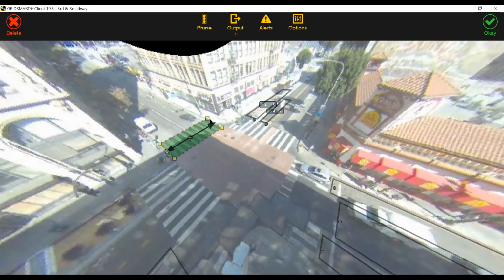Or perhaps a user entered the crosswalk without pushing the button, or maybe the PED button was damaged, and they entered the pedestrian zone, the crosswalk area, and we would be able to provide extensions for that vehicle phase, so there's no conflicting traffic entering the PED zone, the crosswalk, while there's a PED in that zone. So that's our PED zone.